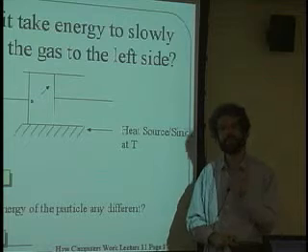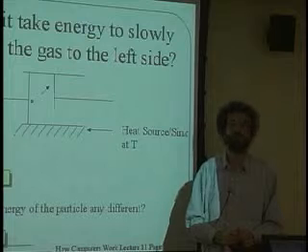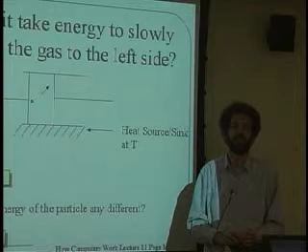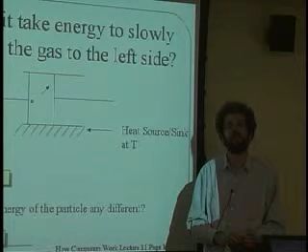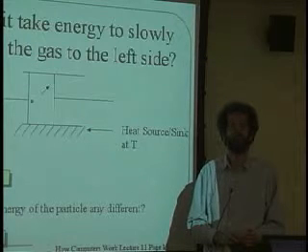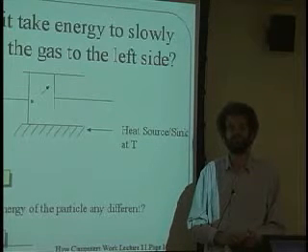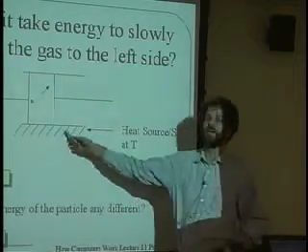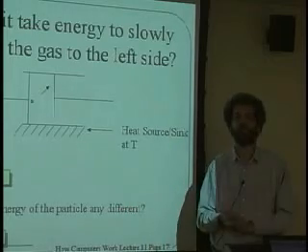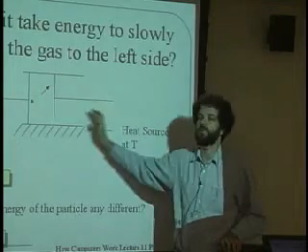Well, in general, in these thermodynamic systems, there are two extreme ways to do it. One is called the isokinetic case, which is what we're going to do, and the other one is the isothermal case. Did I get that right? No, I am wrong. One is the adiabatic case, which is not what we're doing, and the other one is the isothermal case, which is what we're doing. In one case, you hold the temperature fixed by hooking up a heat bath. In the other case, you hold the system fixed by not allowing any heat to get out. We're going to drain all of the extra heat out of the system, so we're going to keep the temperature fixed as we squeeze the thing.